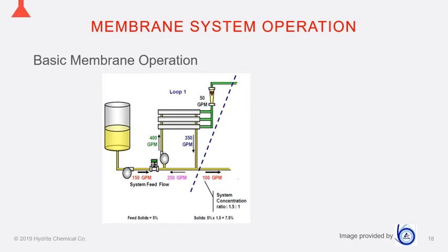By example, you can see on loop 1 that there are 3 vessels or housings. With membranes, there's a lot of terminology that's interchangeable. So you can see that there's 3 of them there. Each of these housings or vessels need a certain flow rate depending on the diameter of them. Many years ago, we would have 3.8 inch elements. We would just typically call them 4-inch. But we see nowadays most membrane systems are either 6-inch or 8-inch. Just means that they're getting bigger footprint, etc.